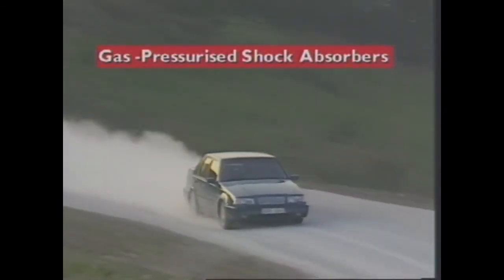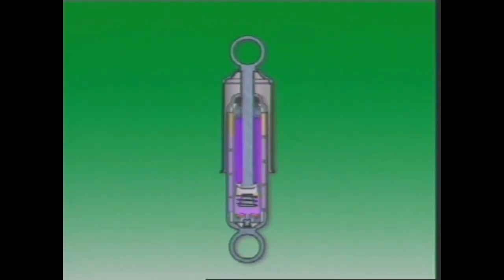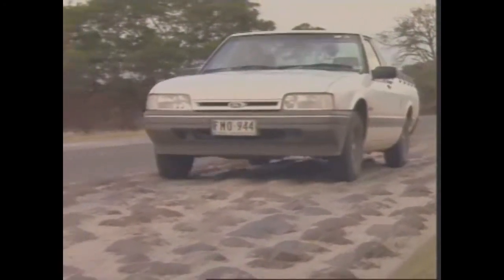This section examines gas pressurized shock absorbers. In a hydraulic shock absorber, the oil heats up as the energy of motion of the suspension is dampened. The rapid piston movement as the vehicle moves over the road causes the hydraulic fluid to aerate. This reduces the dampening effect, and the shock absorber's performance very quickly deteriorates. This condition is called shock absorber fade.